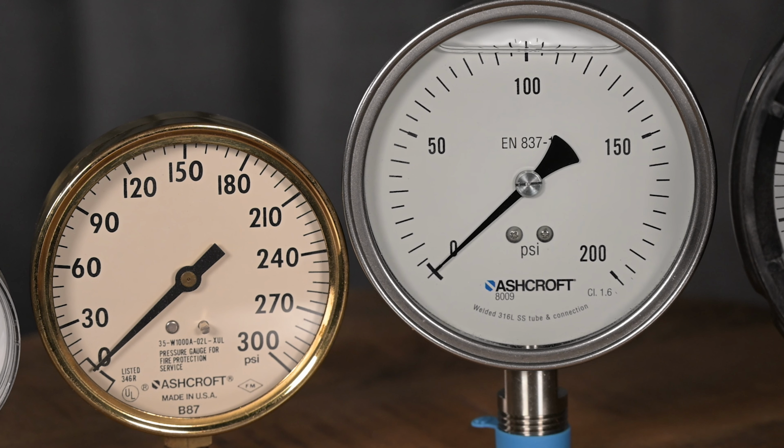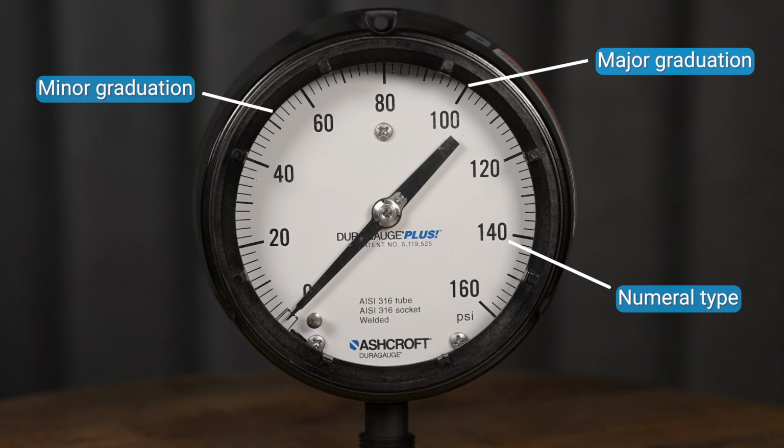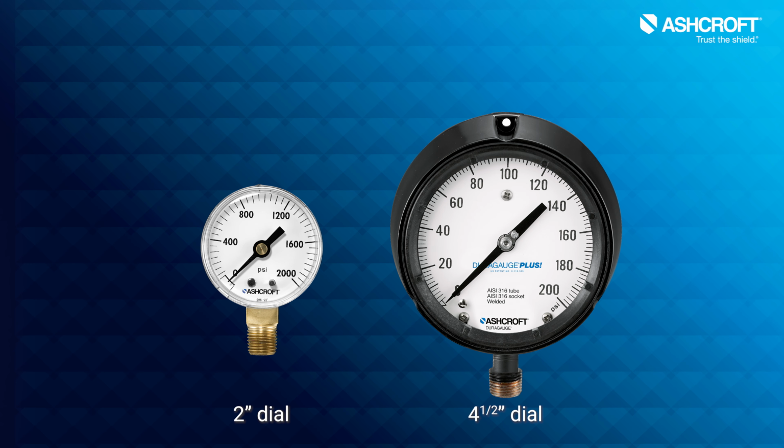Dial features, on the other hand, also consider numeral type, major graduations, and minor graduations. Minor graduations can be difficult to read if too close together, so consider the readability of these smaller graduations when selecting the best dial size. This is important, especially when you choose a better accuracy gauge. The better the accuracy of the gauge, the more graduations are required.